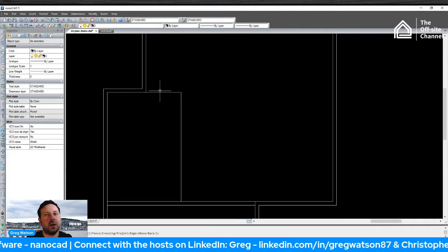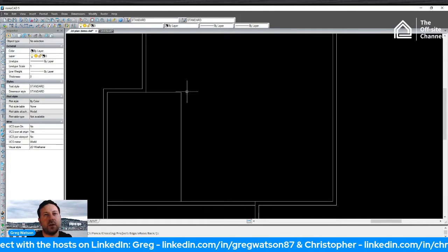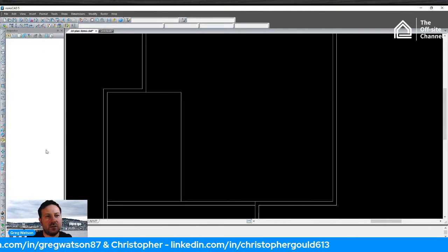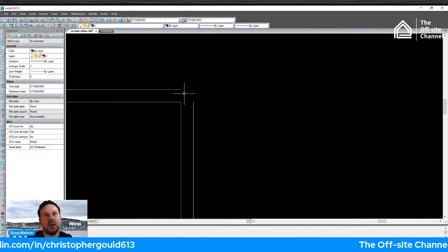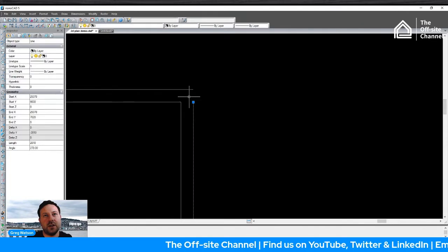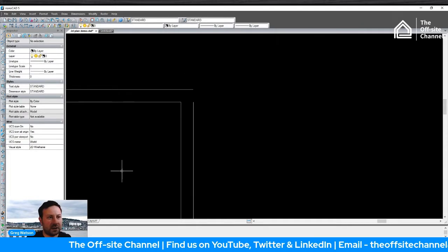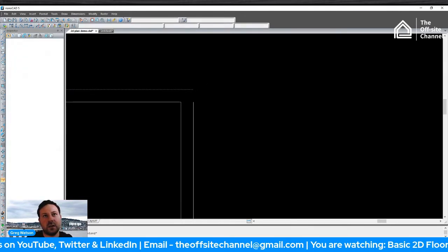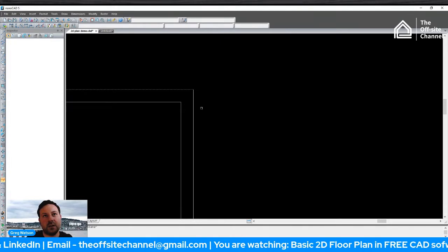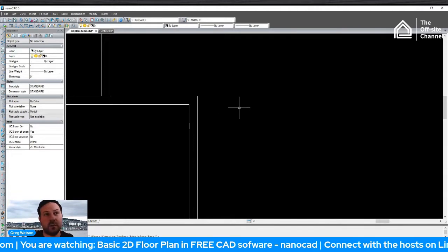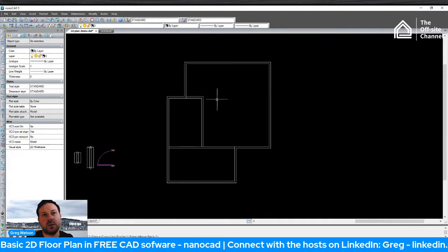Okay. And what we can do is, well, what I'll do is I'll offset those back up and we'll join those with trim extend. Let's do it that way. So 95 here and here. And just drag that. You can also drag it. You can actually do it this way, and then you can join that there as well. Or let's extend that there, and click and right click, enter, and click this one to meet it. Again, similar for the trim function as well. So there's our walls.